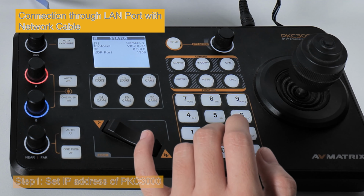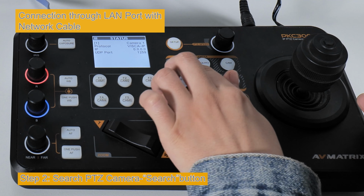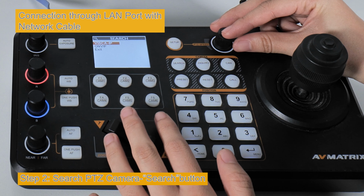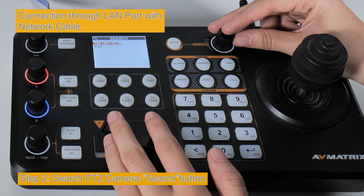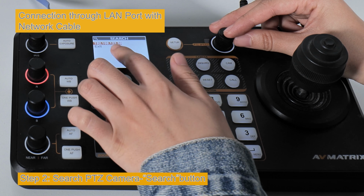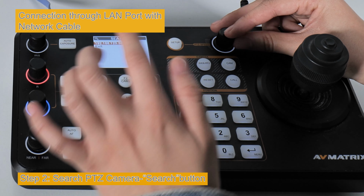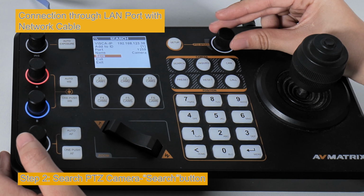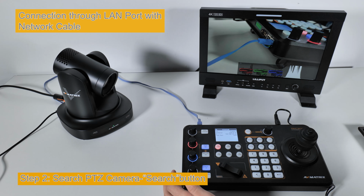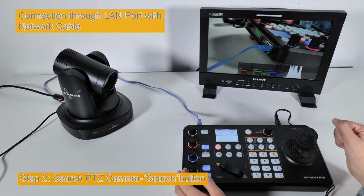Now let's search for the PTZ camera. We can press the search button and choose the protocol VISCA-IP. And as we know, this is the IP address of the PTZ camera we are connecting. So choose it and then press call. And we can see connection OK. That means now we can control the PTZ camera successfully.